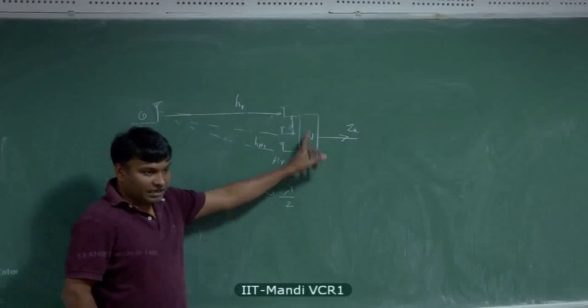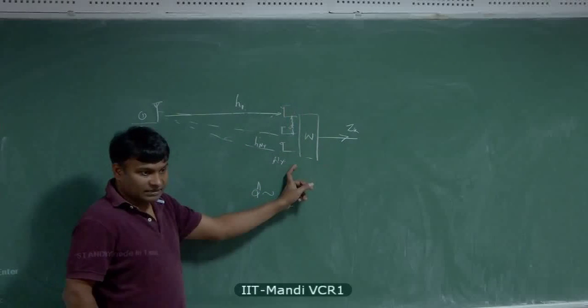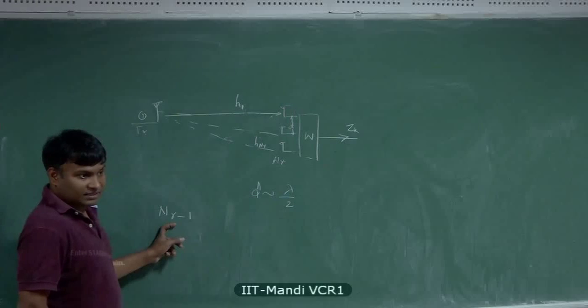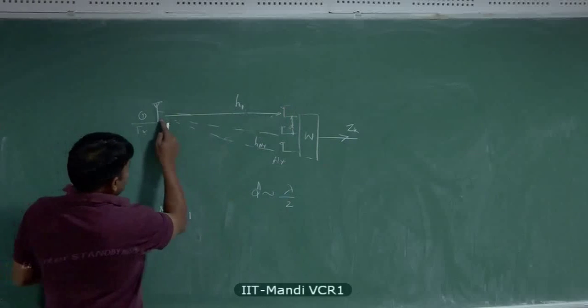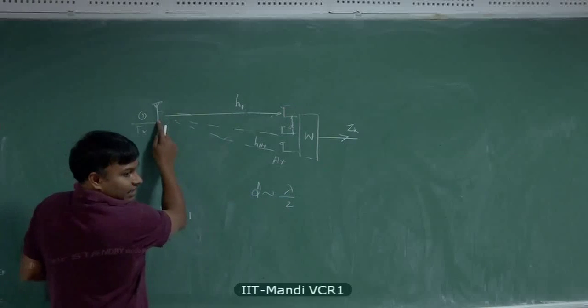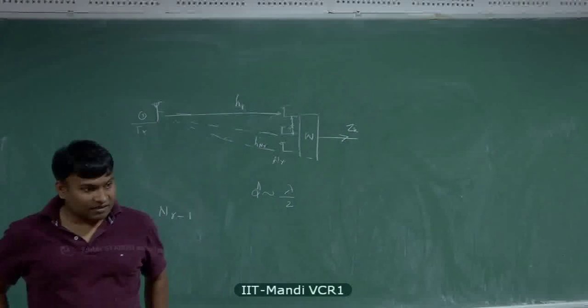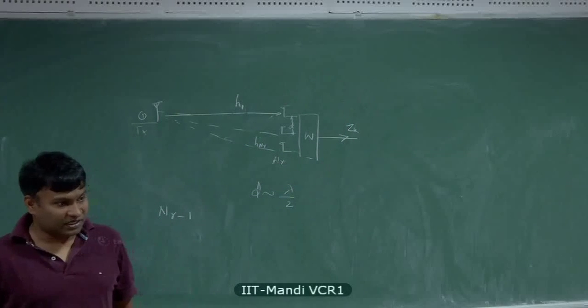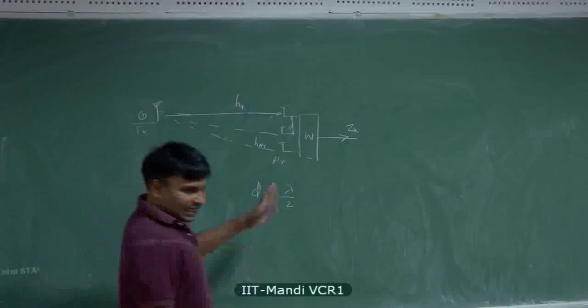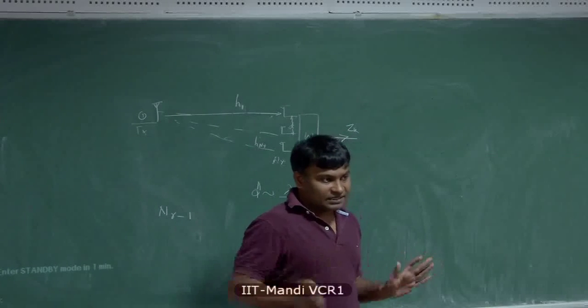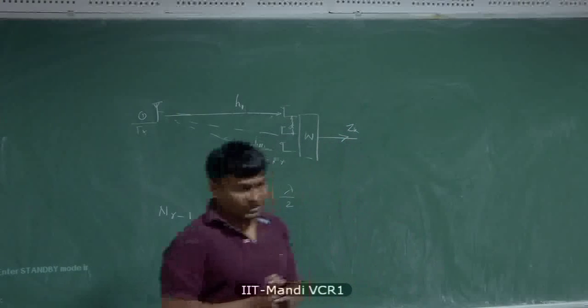If I choose these weights properly and combine the output of these antennas, it's possible to place a null in the direction of those interferers. It's like forming a beam which is collecting energy from this transmitter and placing nulls in the direction of those interferers. That's one way of looking at this problem. That's not exactly how it works, but that's a way of understanding it. So you reject interference and you only capture the desired signal component.